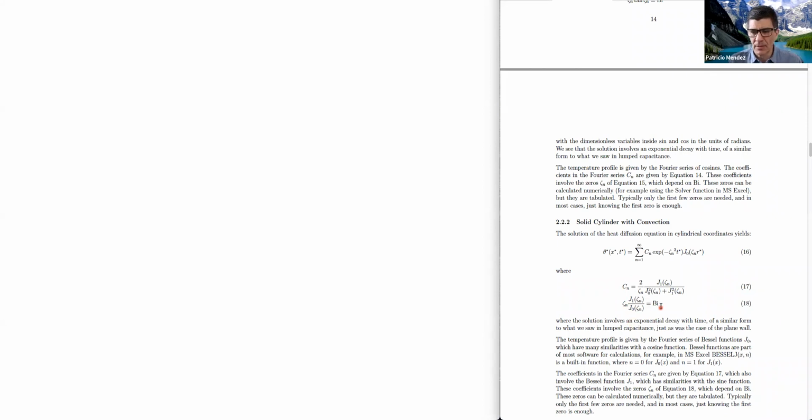You see, if I give you a zeta n, it's easy to calculate Biot. But the problem typically works the other way around. I give you the Biot, and the question is, what is this zeta n? These solutions are tabulated. In the book, you have a list of tabulated solutions.